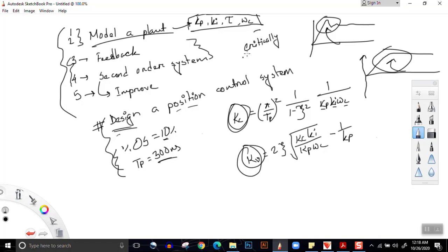If we design a critically damped system, within a very short period of time, even within days or months, it will become an overdamped system, and damping will gradually increase. Damping will not decrease; it will keep on increasing. So speed performance would decrease by a great margin. So what do we do? We create a range of overshoot that is acceptable to us.